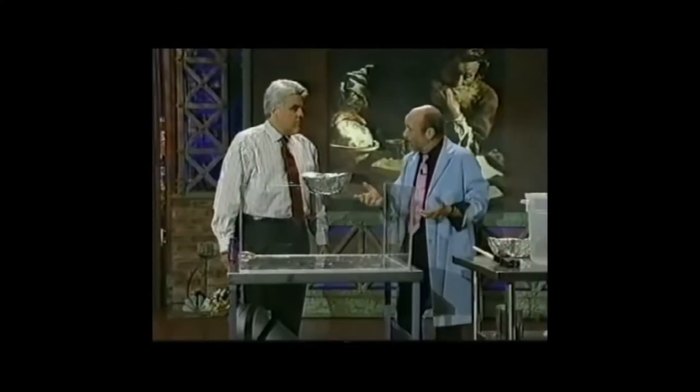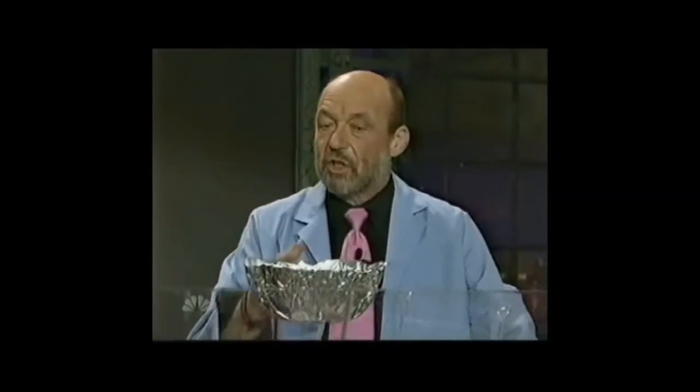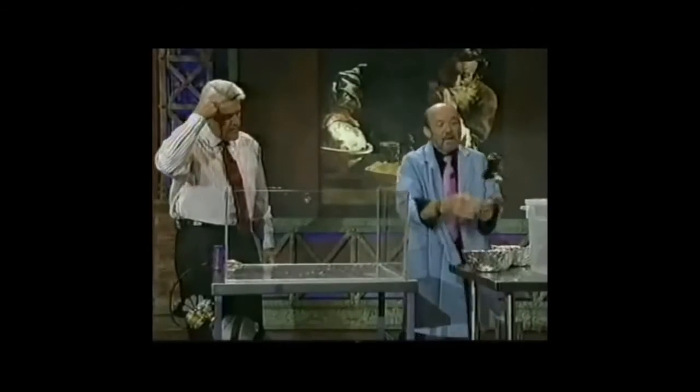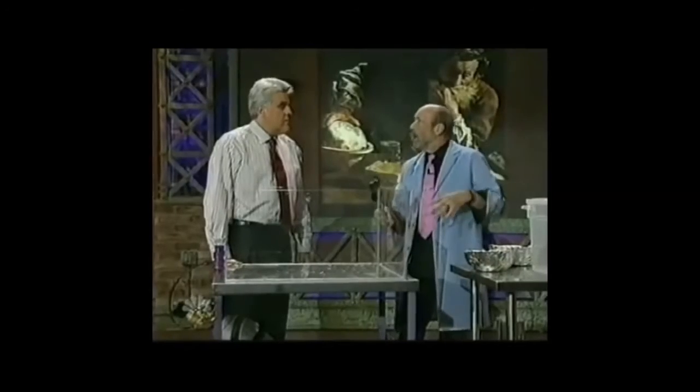What it's used for in industry is in circuit breakers and big switches because it will not conduct electricity. Electricity won't pass across. Now, what I've got here is a 400,000, almost 500,000 volt zapper. It's a stun gun. If I turn that on, obviously don't touch it, watch what happens. It goes out. And when I lift it up, it comes back on again. So this makes a very convenient gas for insulating electrical gear.